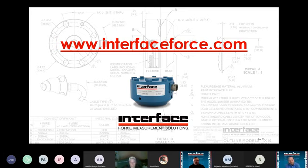But again, on the mechanical preload side, it is important how you preload some of the thread introduction, or excuse me, the attachments, especially for the LPs. As Keith mentioned earlier, it's really important to preload that if you can. That's what we do for best results, so that the load path doesn't change through the threads, which can affect very small amounts of linearity and hysteresis.